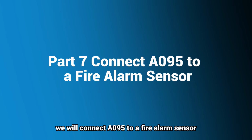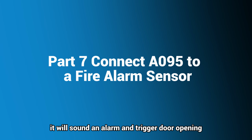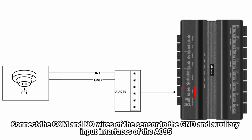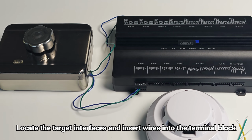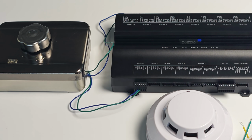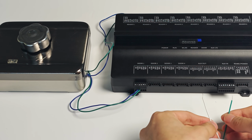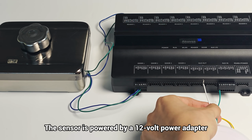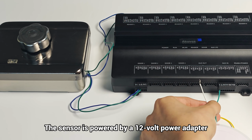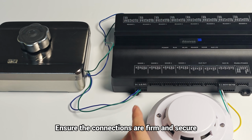Lastly, we will connect A095 to a fire alarm sensor. When the sensor detects smoke, it will sound an alarm and trigger door opening. Connect the COM and NO wires of the sensor to the GND and auxiliary input interfaces of the A095. Locate the target interfaces and insert wires into the terminal block. The sensor is powered by a 12-volt power adapter. Ensure the connections are firm and secure.